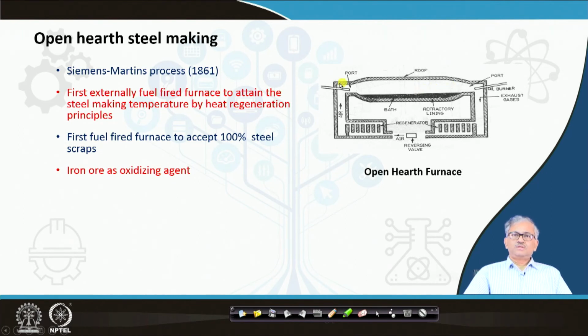And also it is a very quiescent bath, and as a result only when the carbon comes out in the form of bubbles, it generates some mixing or some stirring in the bath. Otherwise it's a mild bath, that is not stirred that much. Only during the carbon coming out, that is called the carbon boil, is there some mixing. So that's why the bath is kept shallow, for the heat and mass transfer point of view. And iron ore is used as an oxidizing agent, that is also a source of iron.